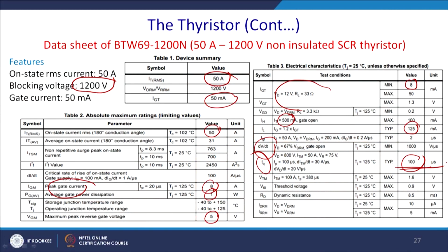In diodes, we have seen a fast diode having a turn off time in nanoseconds, and a snappy diode will have around 1 or 2 microsecond, but this takes a considerably high amount of time to turn off. Turning off these devices is quite slow because of the trapped charges in junction J2. Okay, we shall continue our discussions.